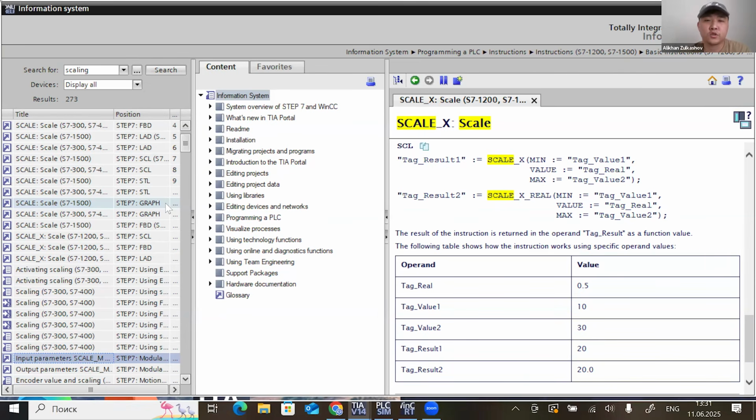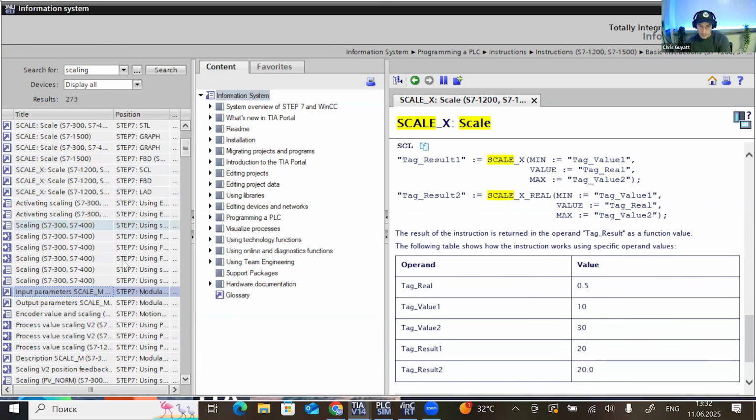The same for short circuit as well, right? If we have a short circuit, it means that our current goes high. It will be above 20 milliampere. It might be 22 milliampere or something like this. Of course, it is as per the NAMUR NE43 standard, which is used for diagnostics of analog input signals. Okay. Cool. Thanks.